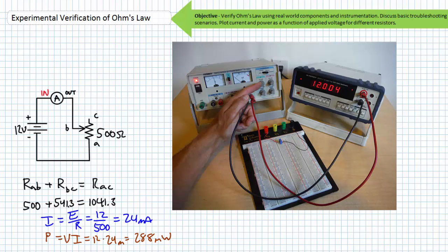Notice my potentiometer is on my protoboard, but I've not yet attached the power supply to the protoboard. What I'm measuring here is the output voltage of the power supply in an unloaded condition. Unloaded means there is an open circuit at the power supply's output and it is not supplying current, because I'm obviously not connected to the potentiometer.